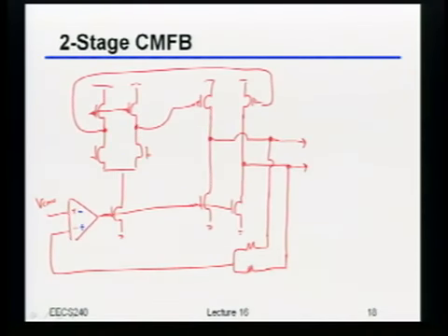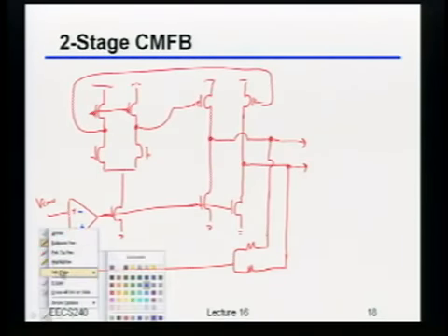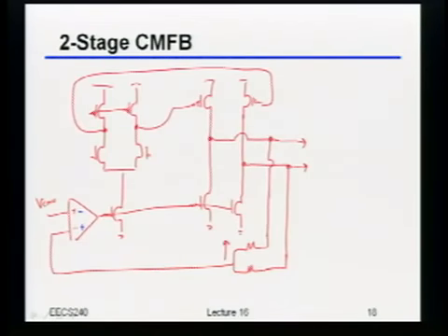The red one? It's the red one. Okay, why do you say it's the red one? Because if the output voltage increases, the NMOS current source current will reduce, which will cause the... Okay, so let's say that this common mode voltage, and I'll do it in red just to be consistent with the colors, goes up, like you said. So you just said if I do the red one, then this will go down. That's right. Okay. So then what will happen over here?